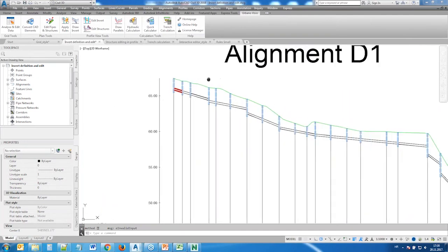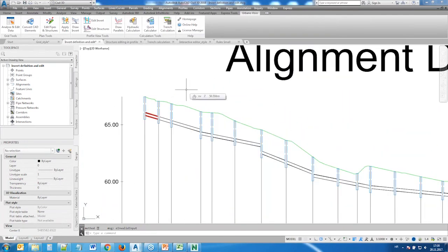What Michael has demonstrated gets us so much closer to the ability to mimic what architects who use Revit have been able to do for a long time, which is embed property data into their objects, so that as you're clashing, as you're building reports and doing coordination, it's a lot easier to identify what kind of elements you have, what properties are relevant to the types of data that are necessary to meet what architects call an LOD, right, a level of detail or a level of development.